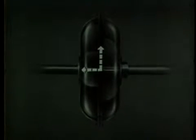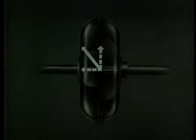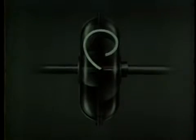Now we know that there is this direction in the oil within the fluid coupling. But we also know that the pump is turning, so there is another direction that the oil takes, which goes this way. Therefore, the effect of this dual motion in the oil would be roughly in this direction. Because of the centrifugal force and the turning of the pump, the actual flow of oil is like a continuous corkscrew that goes round and round inside the fluid coupling in operation.